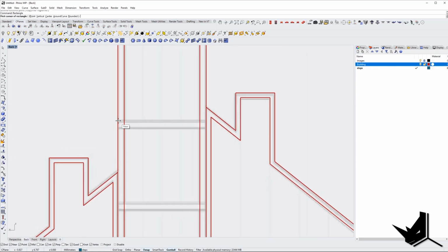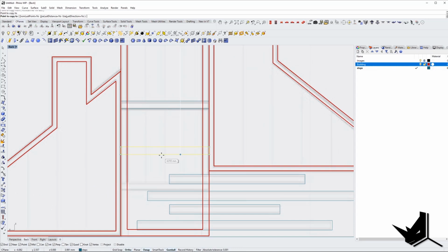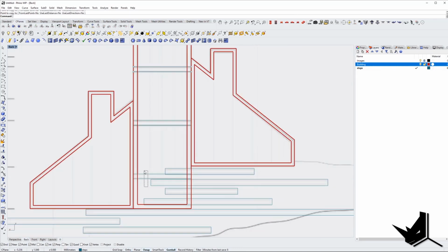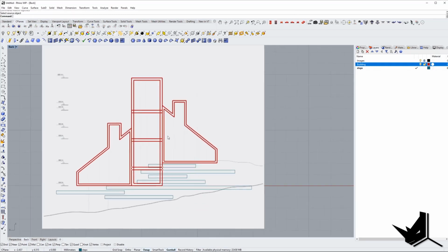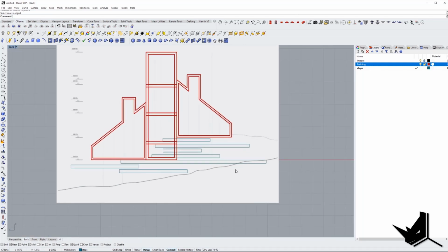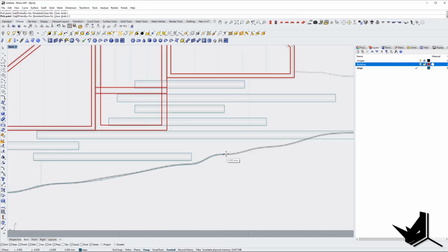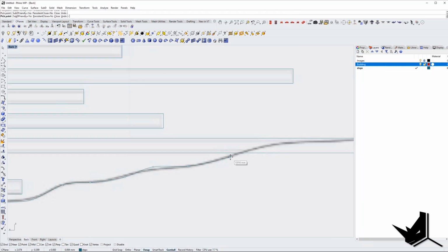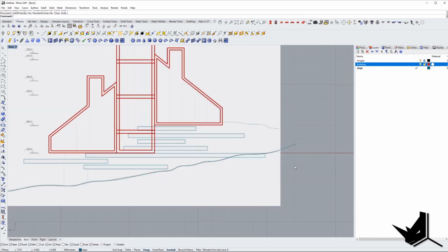What we can do, we can create maybe these rectangles here. And let's copy them. And that's all we're gonna need. Okay. And this will be the part of the building. We can say match properties and use the same layers like so. Okay, so this is fine. And one last thing I'm gonna do, I'm gonna create also this line here as a ground line, just to know later on if I decide to create this ground, I'm gonna try to use this line, or we can use something else, we'll see, but we need the line no matter what.